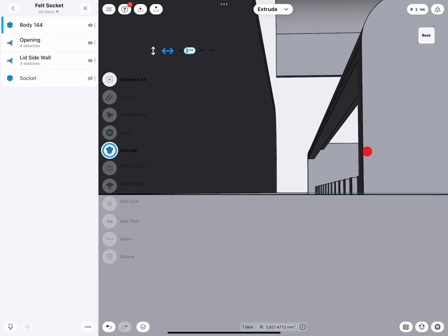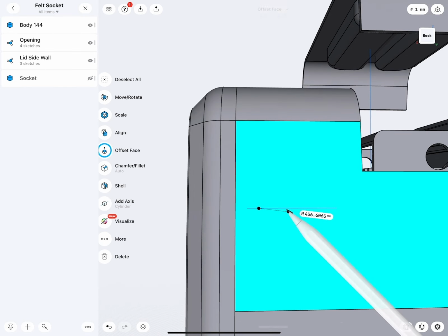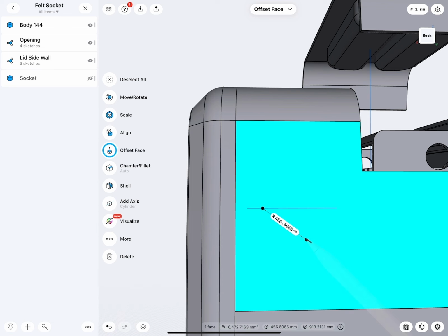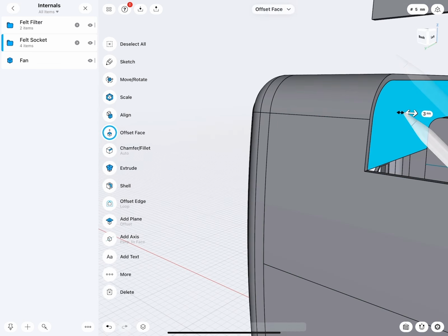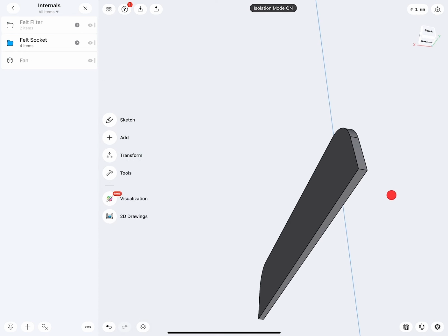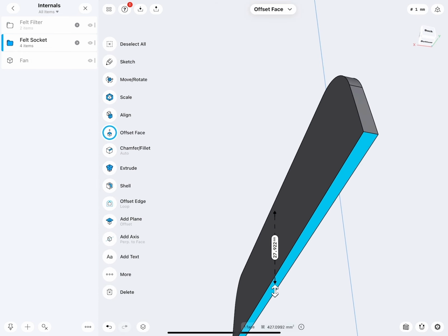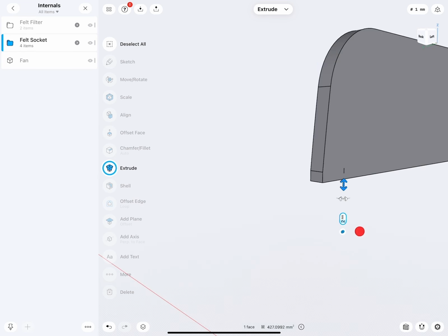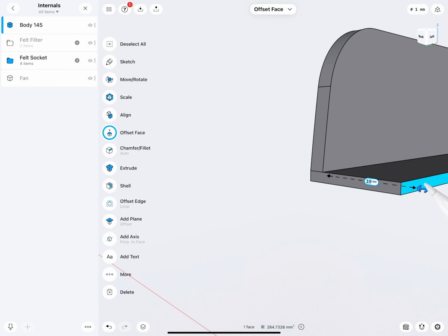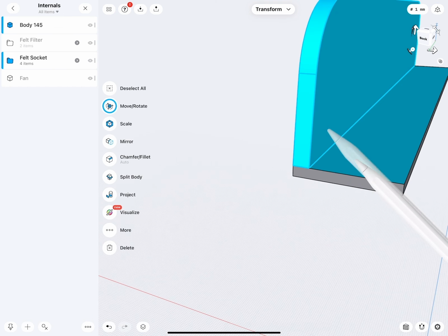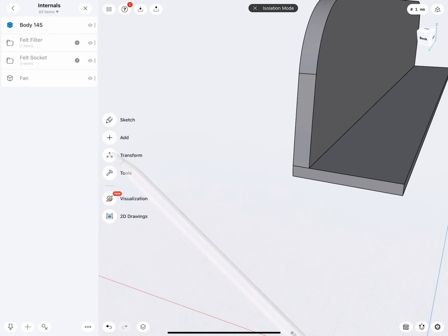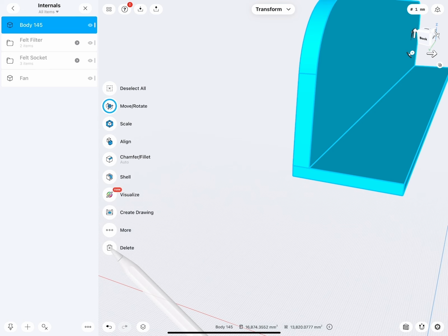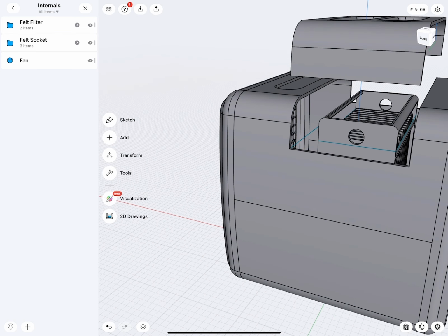And then later, I will just hide. Oh wait, I can do this way. Select this one and say isolate. Beautiful. Then this, I extrude it down by 2 millimeters as a new piece. That's important. And then this I was able to bring over, and then later we join this together. So this is kind of like the way how step by step I build these elements there.